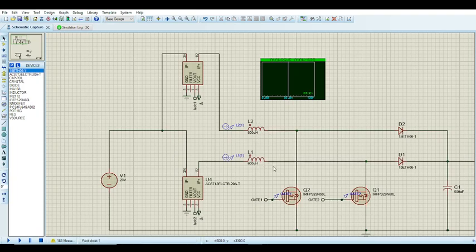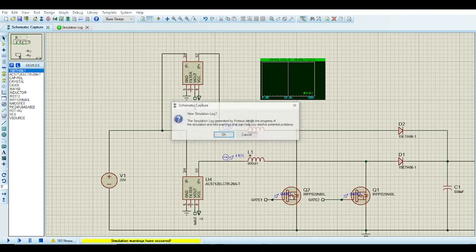But if you think about it, having two inductors takes a big space, but in the case of an active snubber, for instance, you'd have an extra MOSFET to having an extra inductor. I mean, most people would rather have an extra inductor than an extra MOSFET or extra capacitor or tiny resistor. So it's a good trade-off in terms of space. This is just something interesting.